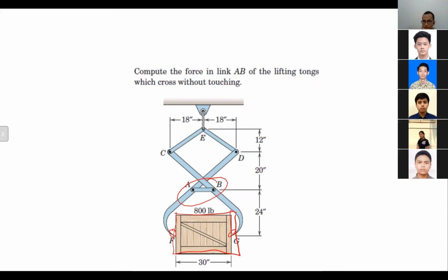We should know the two force members first. Just correct. Actually, before that, you're supposed to understand the problem, and you did. Now the second step is to find out which ones are the two force members. How many two force members can you find here? Three, I guess. What are those? AB, CE, ED. Yes, you are correct. Those three are the two force members.